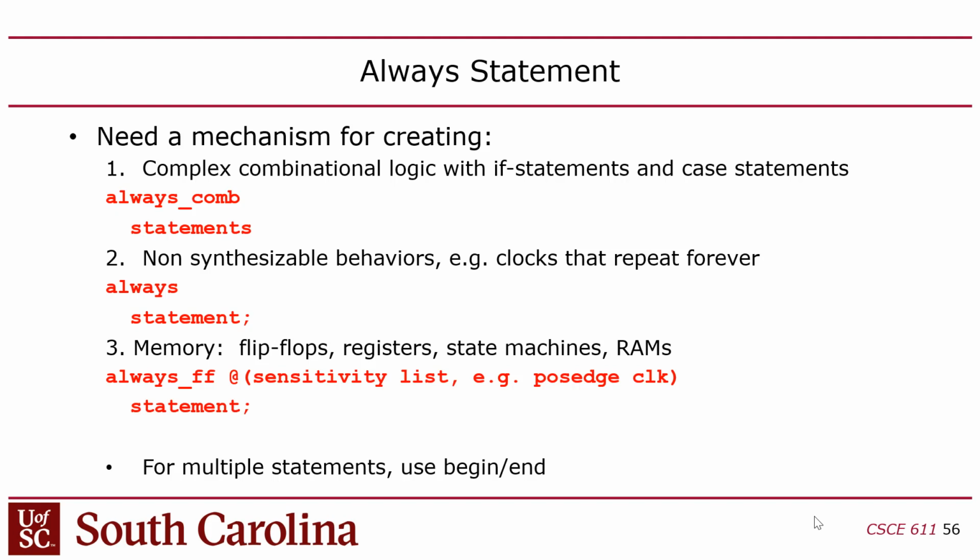Whereas with a latch, you don't get a whole period of the clock. You just get basically the time the clock is low, basically half the period. So your timing analysis from the tools is kind of screwed up, and you'll end up with a much slower clock if you end up using latches. So you should avoid using latches.